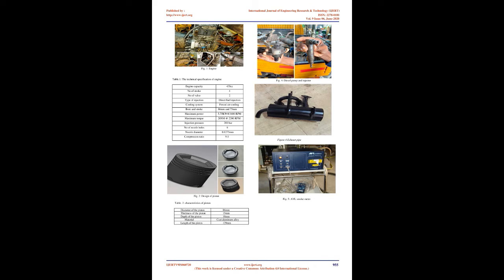This happens when there is a lack of oxygen, so not all of the fuel can combust, and can also be seen in a Bunsen burner. The major drawback of diesel engines is their emission of toxic air pollutants. These engines mainly discharge high levels of particulate matter, NOx, CO, and odor compared with spark ignition engines. Consequently, in the small engine category, consumer acceptance is less.